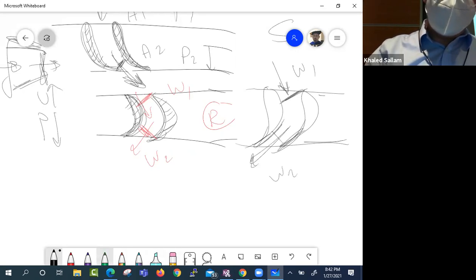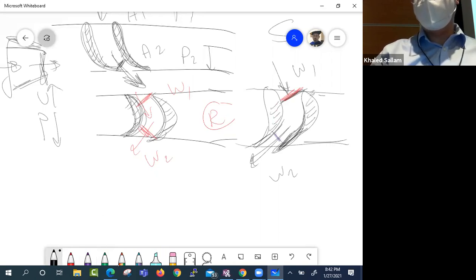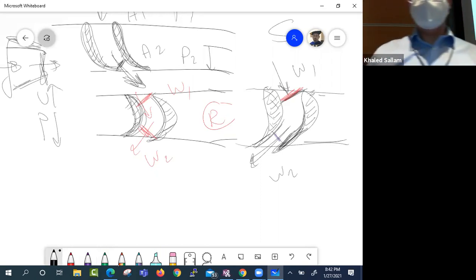So you see a rotor like this, and you tell yourself, wow, look at this inlet area, and look at this smaller exit area. Especially if the plate is really big, so that it's a little bit full. So this would be a reaction turbine, okay? Because the flow will accelerate as it goes through the rotor too, the moving part.